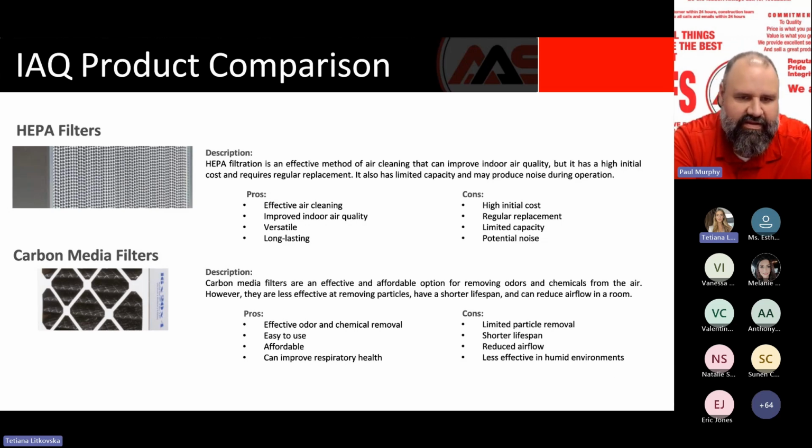So then the next one is carbon media filters. We use carbon media filters for trapping odors. So if we have a client that's got an odor issue, we'll typically throw in some carbon media filters to go ahead and get rid of that odor and resolve that issue for them. So they typically don't use them for just normal filter media. It's mainly just used for that odor removal. But you can use them as normal filters. They're just more expensive than your standard foam and fiber filters.